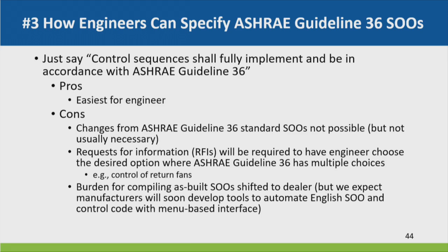You're going to get some RFIs because in the guideline there's some choices. So I can control return fans one of 2 different ways. We have a third way coming up. And the controls contractor will say, well, you didn't say which way you want to control the return fan. Which way do you want? And you say, well, that doesn't matter, right? I mean, it's an RFI, and you just say, OK, we'll use that way.